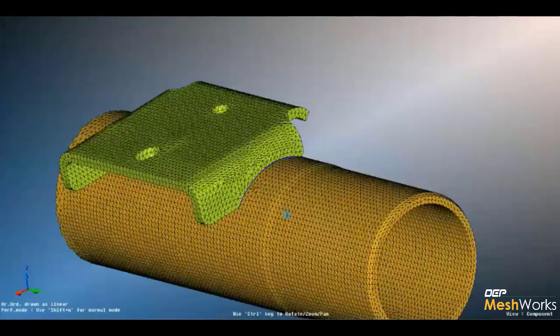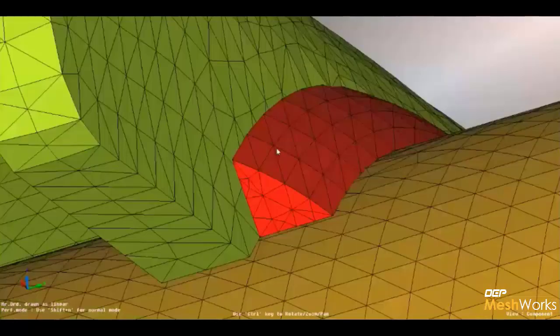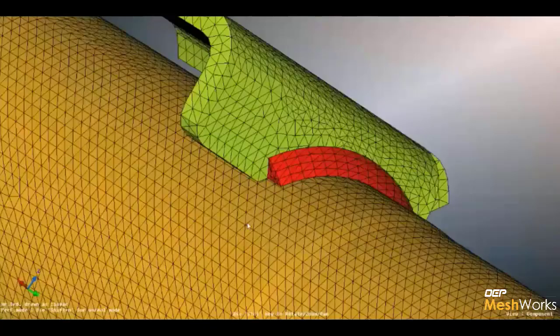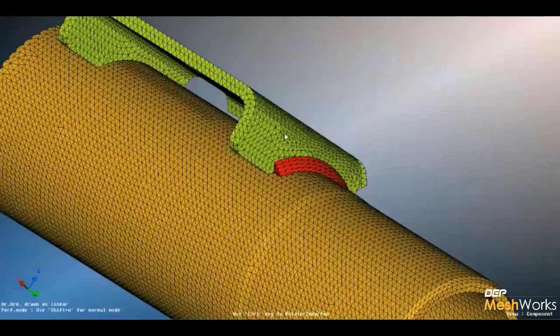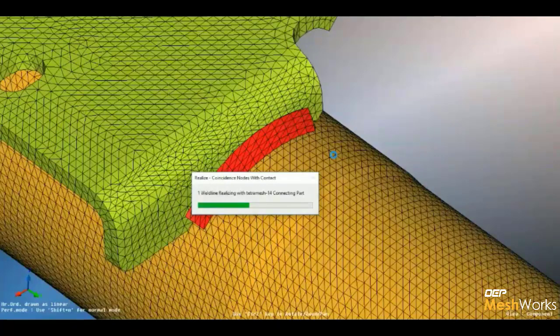Taking the solid weldment as an input, the preview is created. In this case, there is no nodal connectivity yet, and here you can see a convex profile weld with all the inputs given in the solid weldment. The moment we say realize, the tool starts creating the node-to-node connections with the base components. And the beauty here is that in tetra components, people nowadays create layered tetra mesh.